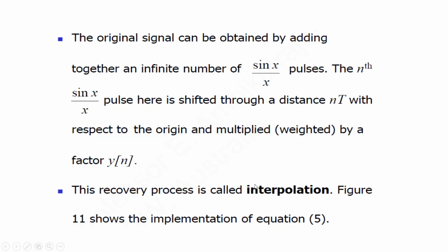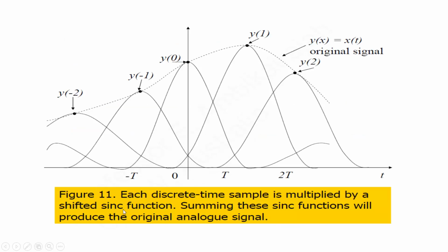Now this recovery process is actually called interpolation. We will see in the diagram what this interpolation process is. If you see the curve corresponding to y of 0, this sinc function corresponds to y0, right?